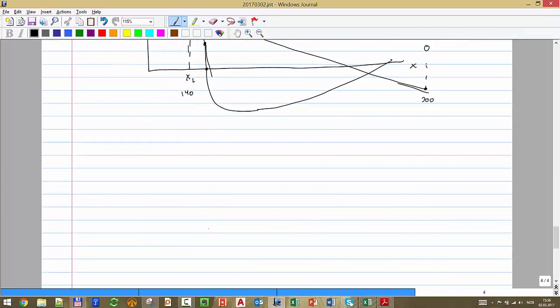Okay, let's look now just at that system that has two wells, the flow line, well, actually more wells, and here I have a common pressure, the pressure at the junction, right? Imagine for a moment that P junction is given. Can I solve that system? Can I calculate how much is being produced by well 1 and well 2? Yes, right? No problem. Now I will solve it and I will get a certain total rate.